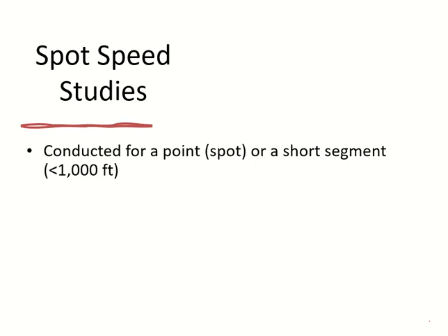The word spot means that the study has to be over a spot. Spot means a point. Now keep in mind, I'm saying spot speed studies, because there are other speed studies as well which are not spot. So now we are especially discussing spot speed studies. A spot means a point. So by default, you need a speed measuring radar to do these studies.